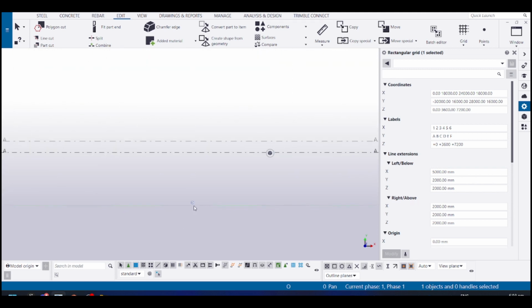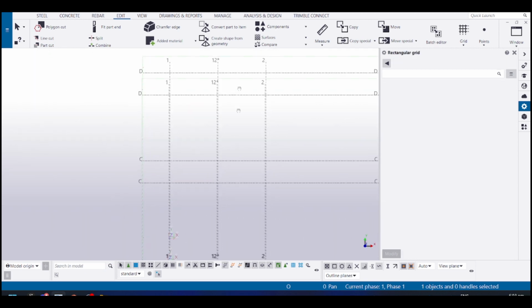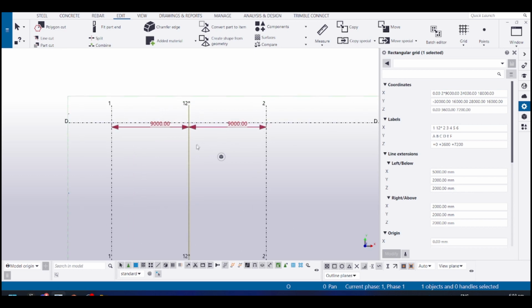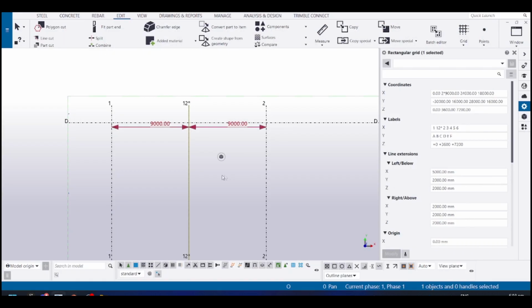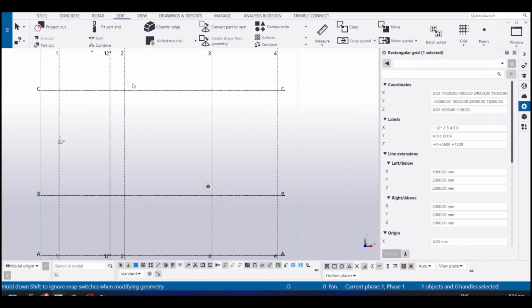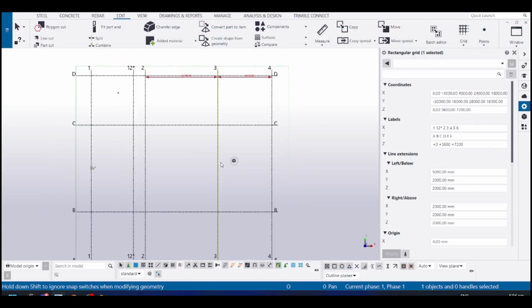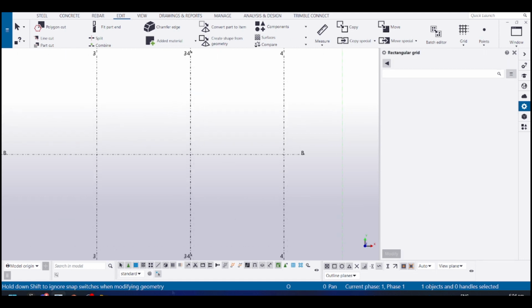So you see this plus, when I hit this plus, it's very tiny in this version for some reason. Okay, it created a new grid line and we want this grid line to be at how much of a stair core is that? Is it 4 meter, right? So let's just keep it 4 meter from this side. Okay, so this is done, and we do the same thing on the right side. Click here, and it is a very tiny plus sign. Hit that.